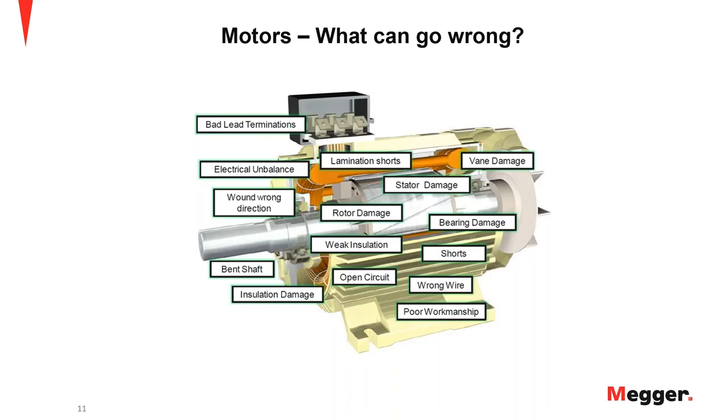So we have rotor damage. Rotor damage, I just went over that one, sorry. So stator damage, an example of stator damage will be single phasing in the motor. It could be due to the loss of one phase of the three-phase supply, and this could burn the stator winding up if not taken care of with the proper protection.